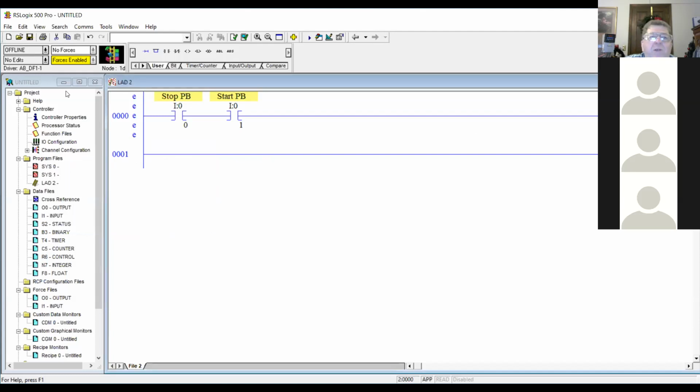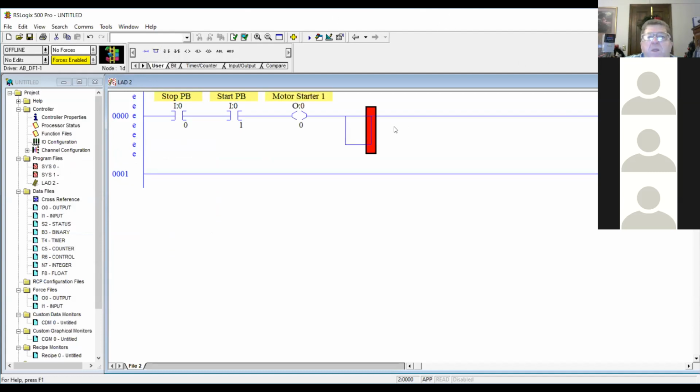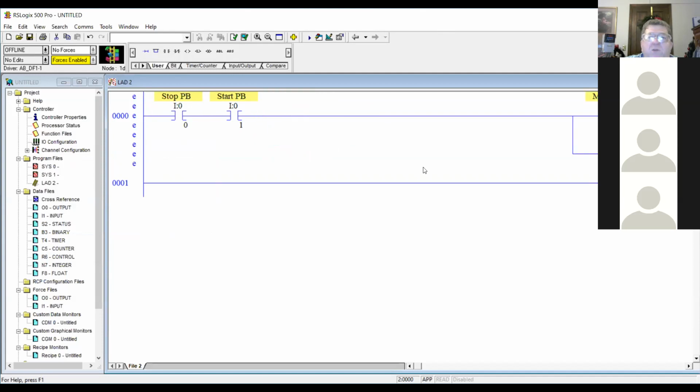So now we're going to create it the same way that you did. We're going to get a branch. We go up here and get a branch, and we go around it. The way you write the logic is the same way; you already know how to do it. You just need to learn how to put the addresses in manually, and the right kind of protocol for that. And we're going to do a timer.